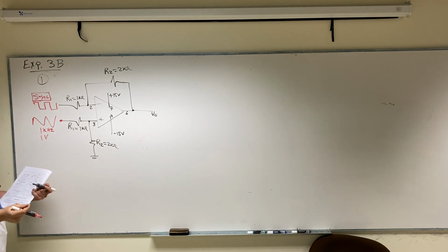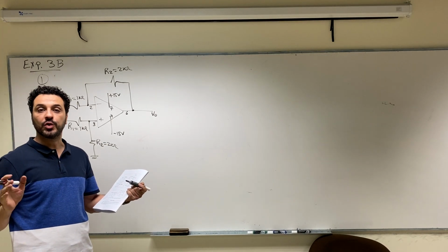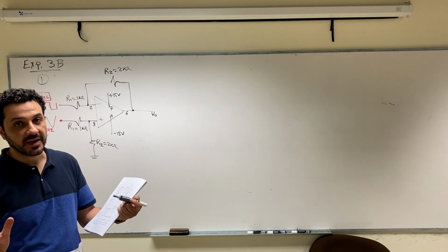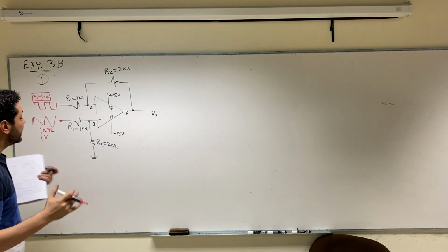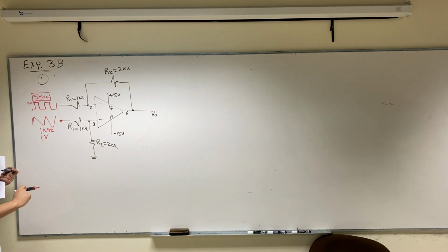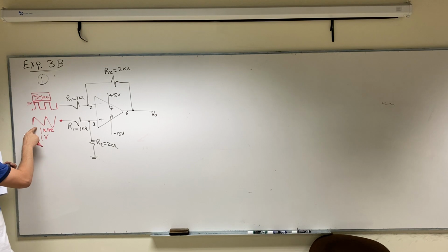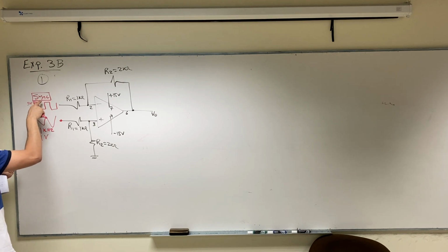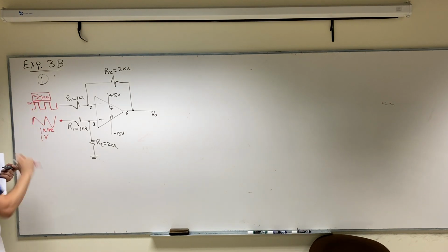As we said before, for this square wave we have no control over its parameters, which means that it always goes from 0 to 5 volts, and its frequency will be the same as the frequency of the triangular wave. So we'll have the triangular signal from the function generator, and from the sync output we'll have this rectangular signal connected like this.